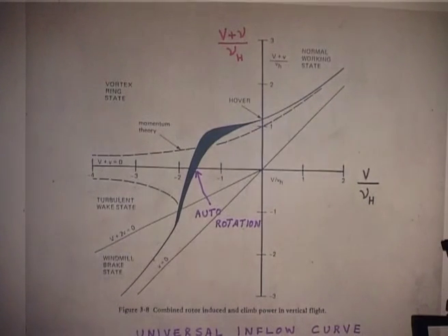You follow what I am saying? All those things can be there: the tail rotor takes some power, and then these losses are also there. That is why industry has an estimate, they will say total power. But what we are doing is only the rotor power. I am not considering my transmission loss, I do not consider my tail rotor; tell me what power my rotor alone will have, real power.